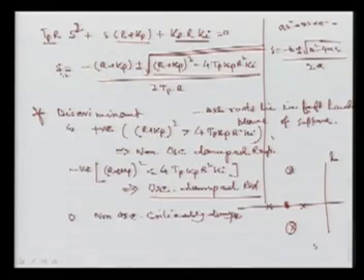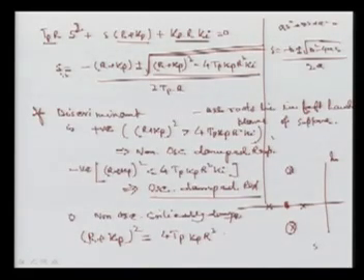Here we get the value of Ki critical: (R plus Kp) square will be equal to 4 Tp Kp R square Ki critical. Others are fixed, and only Ki is set in such a fashion that the discriminant value is 0, and we get critically damped non-oscillatory performance.